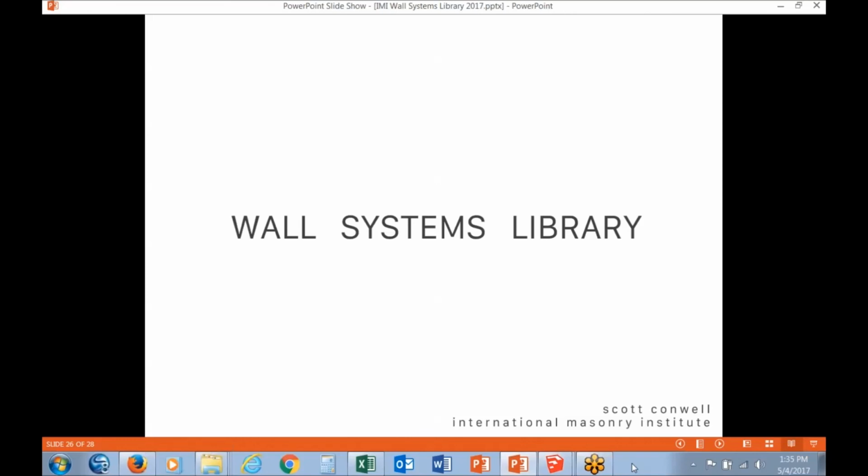We're not even considering the structural framing. Of course, it's a building, and the building is a system, and that's important information. But this is limited in its scope, and that's the same reason why we don't show flashing or terminations and things like that. It does not follow MasterFormat, but these numbers are contained within Uniformat. I don't recall the ASTM standard number, but there's an ASTM standard called Uniformat that classifies building systems, and it's independent of MasterFormat.